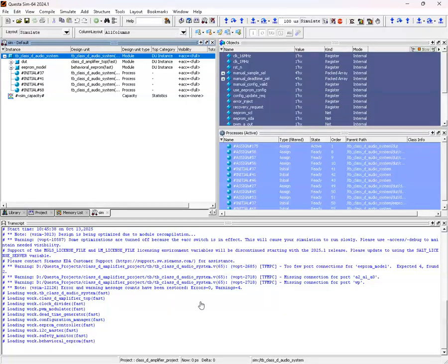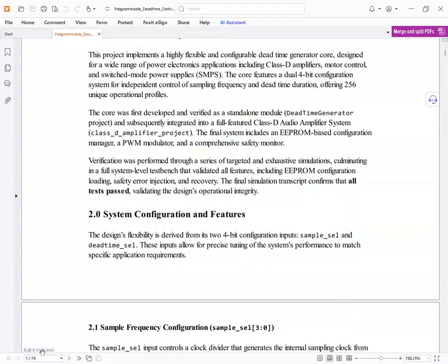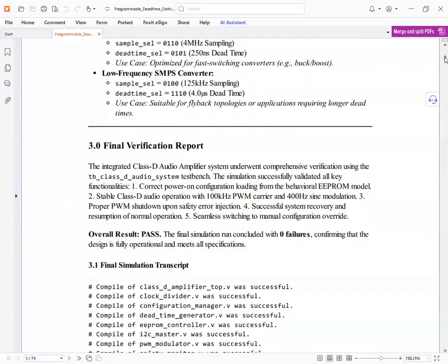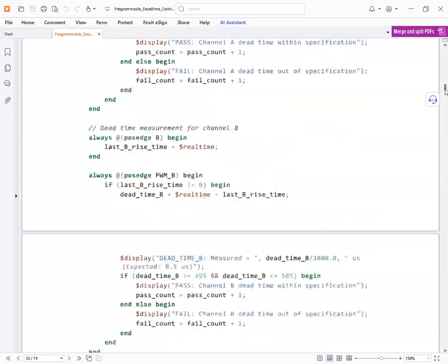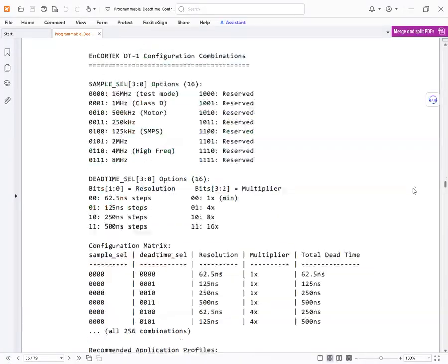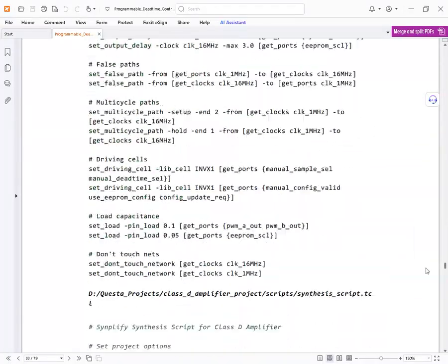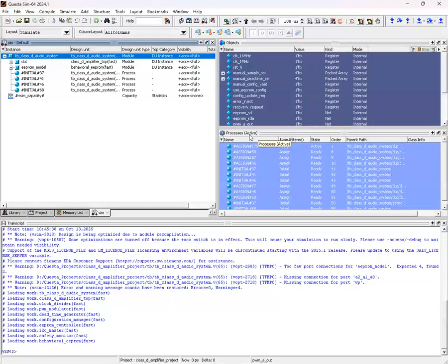So for the synthesis, the design itself that I have, this is my documentation, say 80 pages. You have to document it yourself. And this is the test bench, and the design itself, a bunch of files. This is hardware description language, so you're pretty much describing your hardware in a logical way, and this will synthesize into the schematic you see for analyzing and seeing what's going on. This can be run for simulation, and also be synthesized into transistors, when it's time to do that.